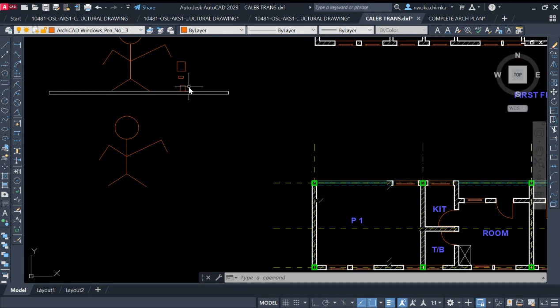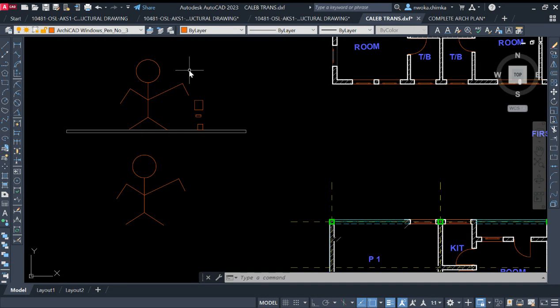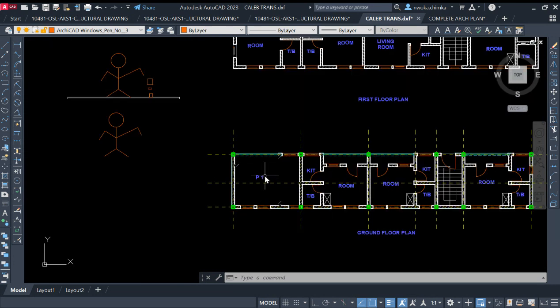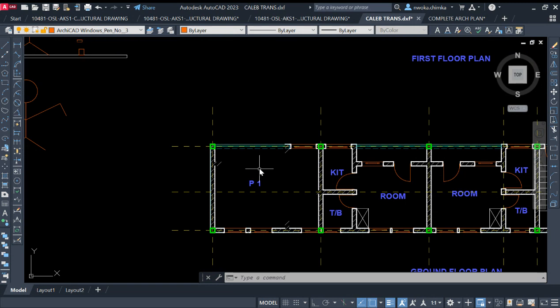there will be a vibration pathway through. So if someone at this first floor throws, let me say, a cup or a plate on the decking, you downstairs will be able to hear that vibration, or that sound, which is not meant to be so. So that is the kind of effect you have if that slab didn't sag or deflect. But if it is far, let me say you're up to 40 meters square area, there will be a deflection on that slab. So to be able to control that slab, you have to provide what they call an internal beam, or a concealed beam, to cut that panel into two.